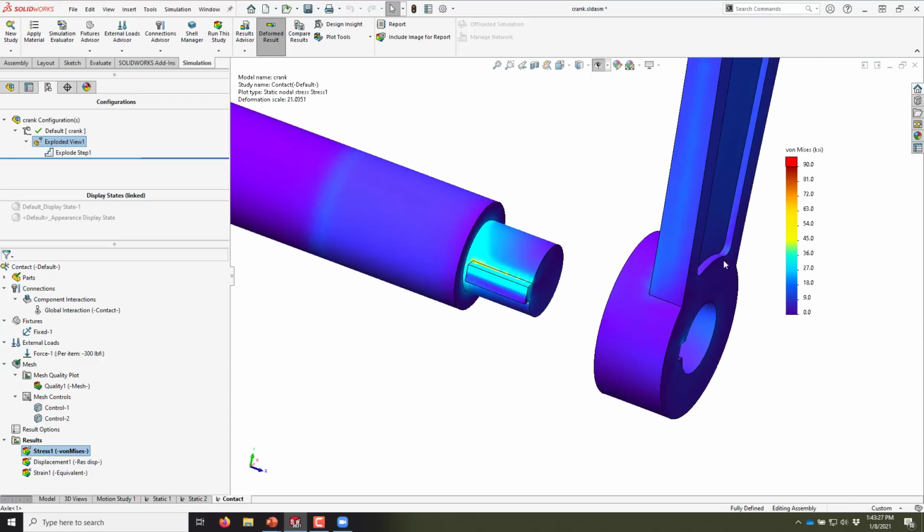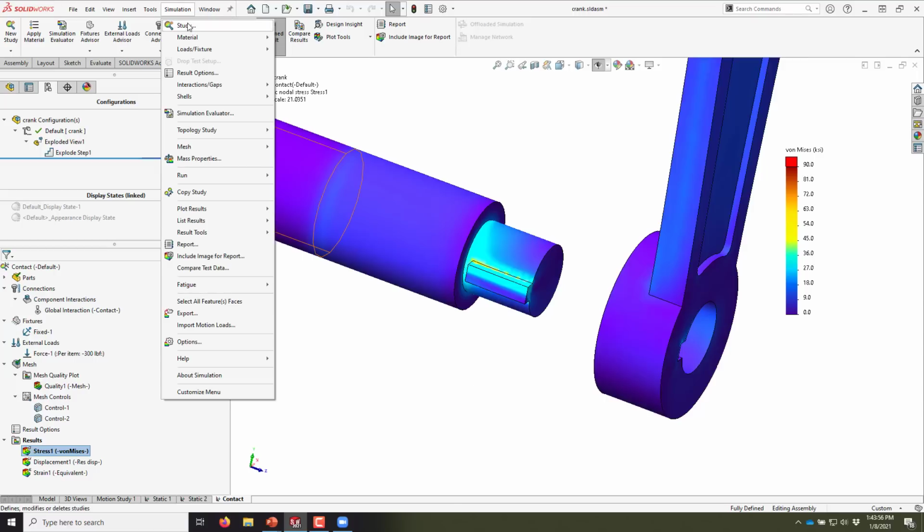But they do appear to be under the yield strength. Looks like we have a safety factor of about 2, I would guess, somewhere in that ballpark, seeing the yellow here. But does that mean that it's going to last a lot of cycles if we cycle this thing? Maybe I'm going to get a crack that develops there and grows. So we have a fatigue calculator that's going to take into account cyclic loading. It's going to compare our stress result to an SN curve. So let's show that part of Simulation Standard, this fatigue calculator.